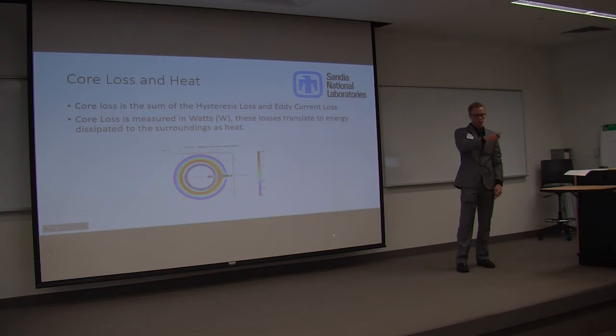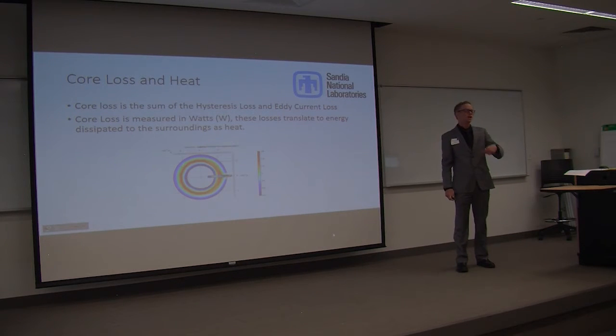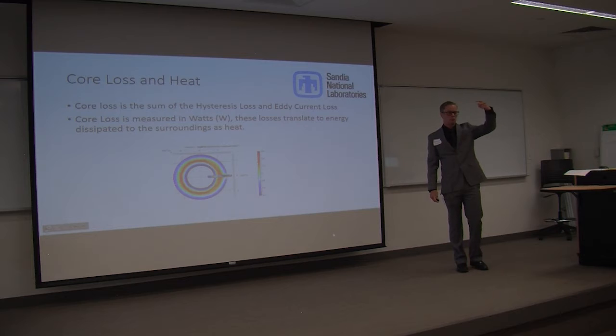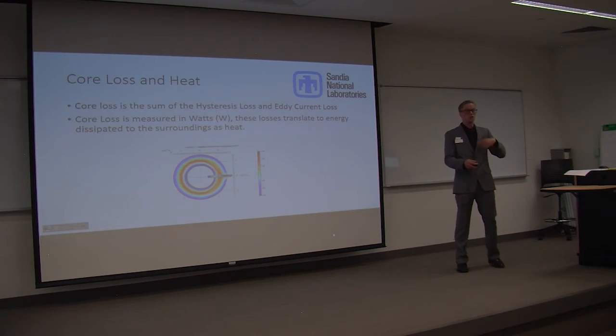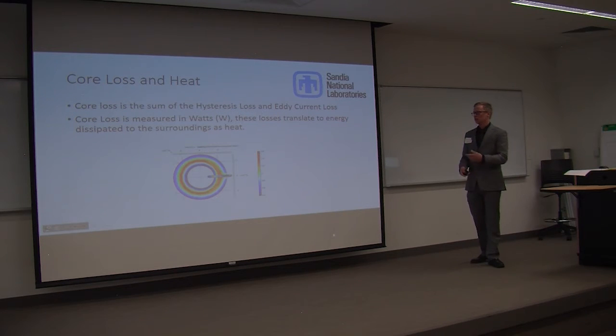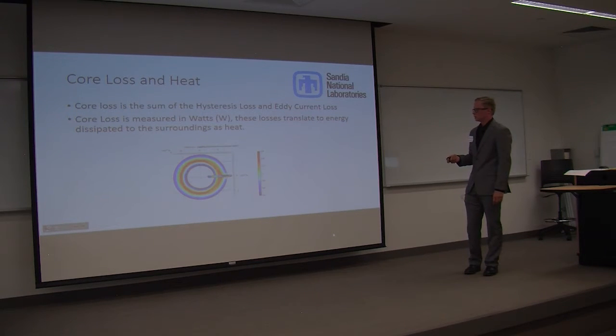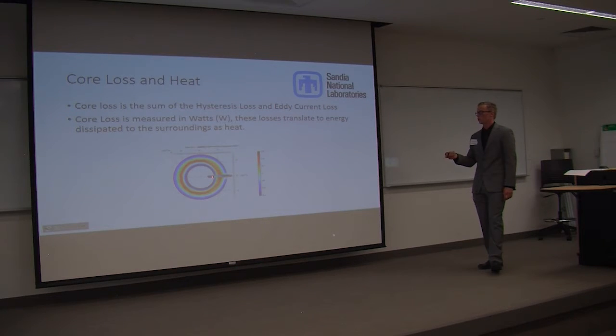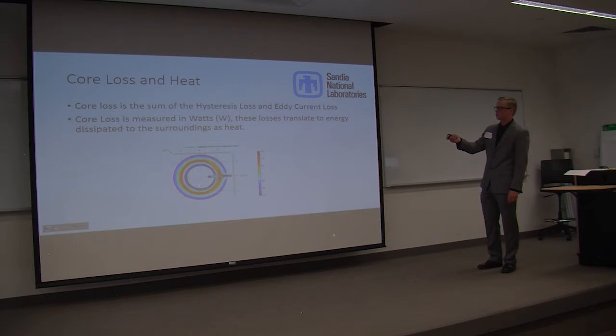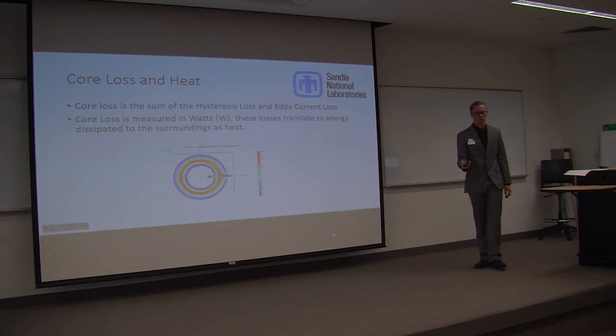As the current is flowing around the inductor, there are these eddy currents that go circular around the current. And then when it switches, they switch. So this causes a core loss as well, which again is dissipated as heat. And this is a pretty interesting picture. Here's the heat flux magnitude. Just looking at the heat, where the coil is located, the copper coil, we have a bit of discrepancy, but as we get farther away, it's pretty symmetrical, and it kind of equilibrates to how it dissipates the heat in the inductor.